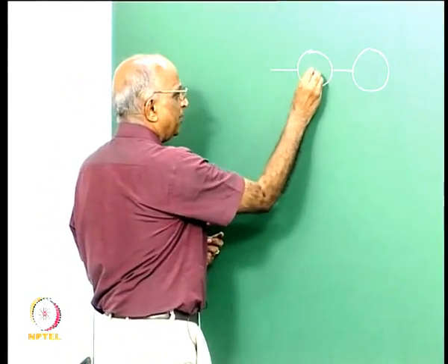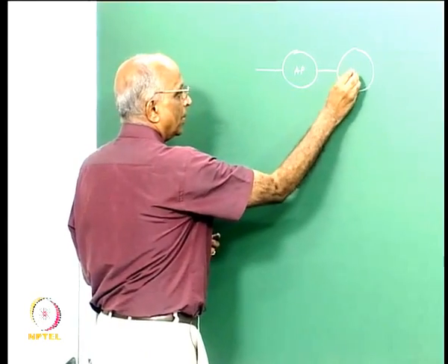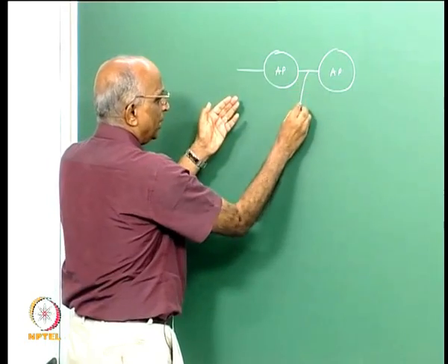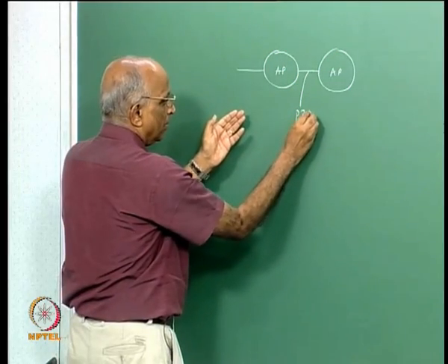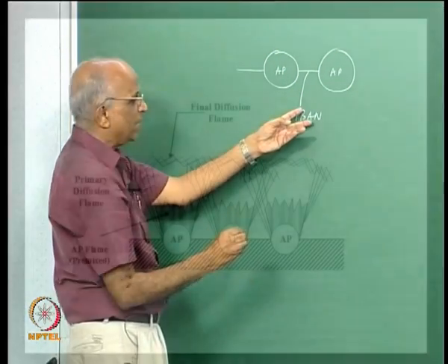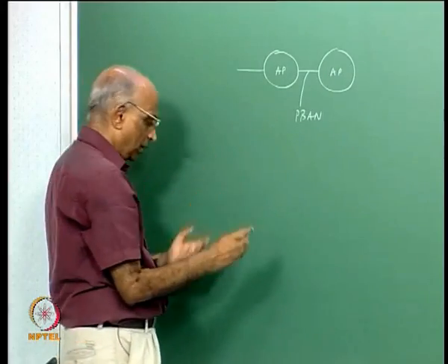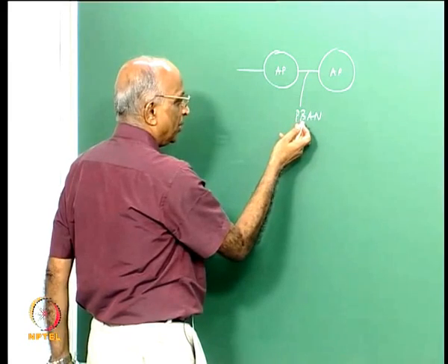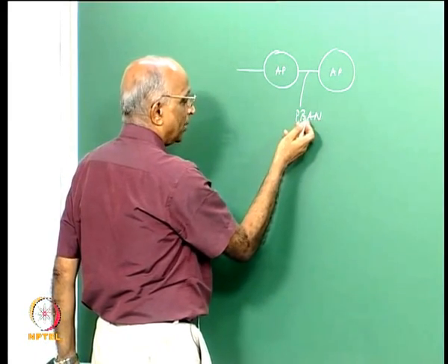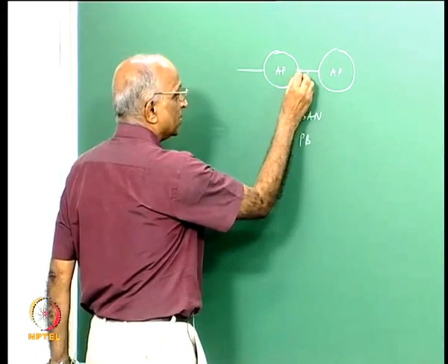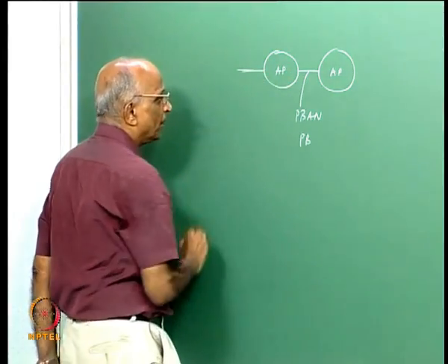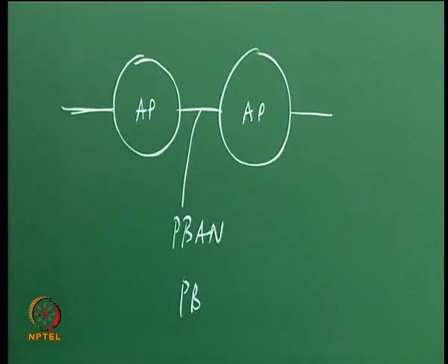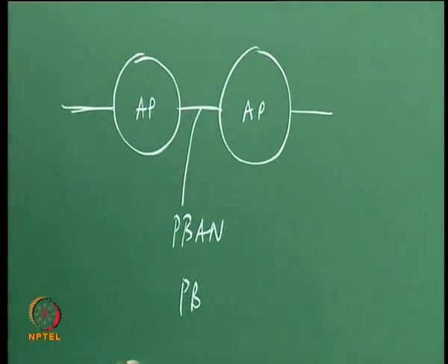Therefore you have something like AP solid crystals, and in between maybe it is bonded by the polybutadiene, let us say p band, and this p band could be some polybutadiene, it could be polybutadiene acrylic acid acrylonitrile, or it could be HTPB, it could be CTPB, this is the fuel or the binder. And when I supply heat and start making this burn, you know AP is NH4ClO4, right.